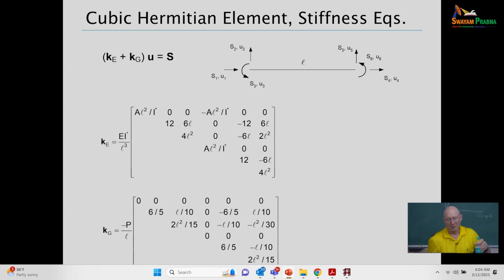And the solution is achieved by starting out with a displacement function for the element. We're going to represent the element response by a cubic displacement field along the length. The true analytical response from the differential equations is not a cubic when we have axial force on there, so it's an approximation. But the whole mantra of finite elements is, yeah, it's always an approximation, but you need to use enough elements and you have a good solution, right?